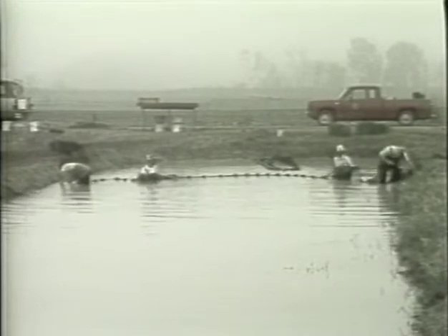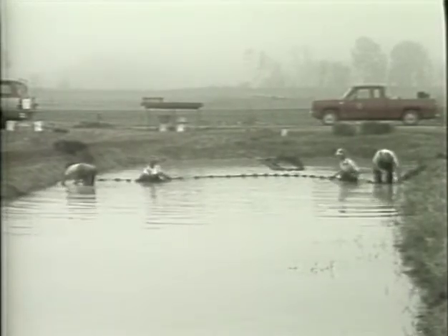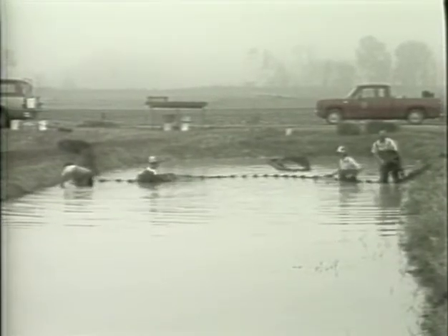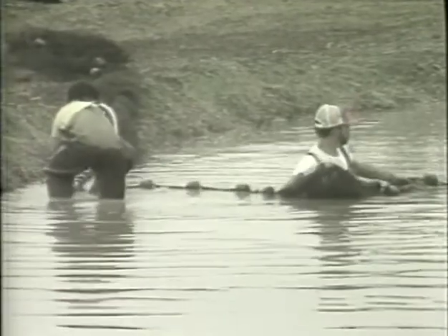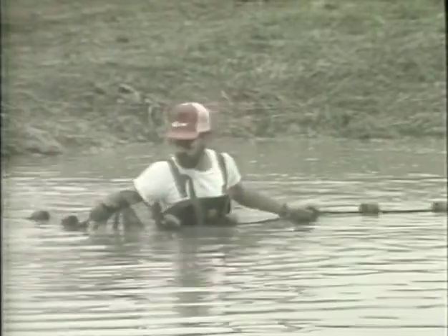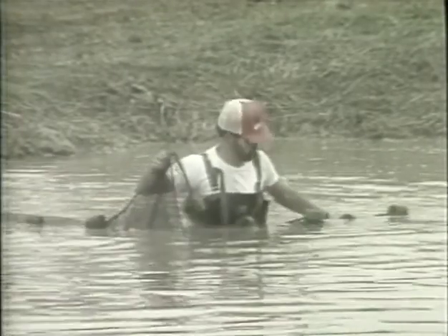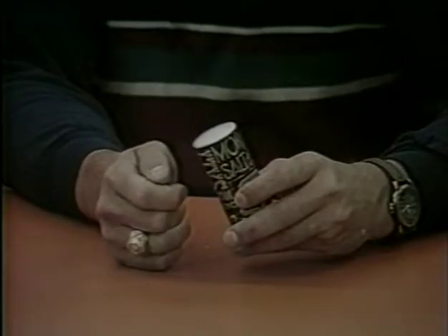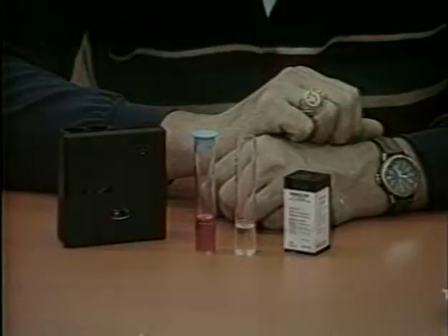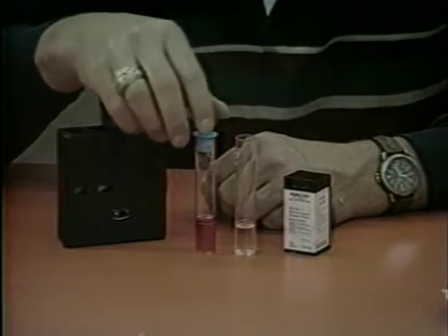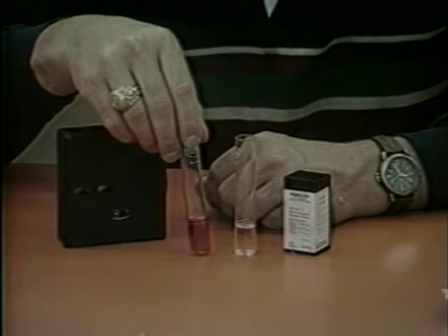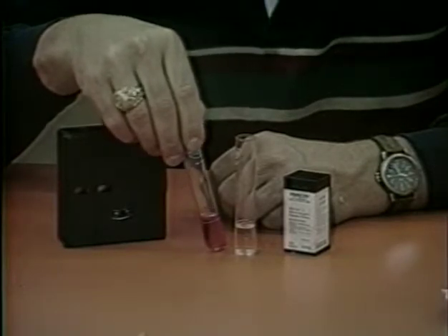Since nitrite levels are related to the ammonia levels, corrective and preventative measures for ammonia apply to nitrite as well, with one exception. Since the toxicity of nitrite depends largely on the amount of chlorides present, the addition of chloride, usually in the form of sodium chloride or common table salt, may prevent deaths due to nitrite toxicity. If nitrite levels are found to be 0.5 milligrams per liter or above, your water should be checked for chloride to see if enough is present to prevent nitrite toxicity.